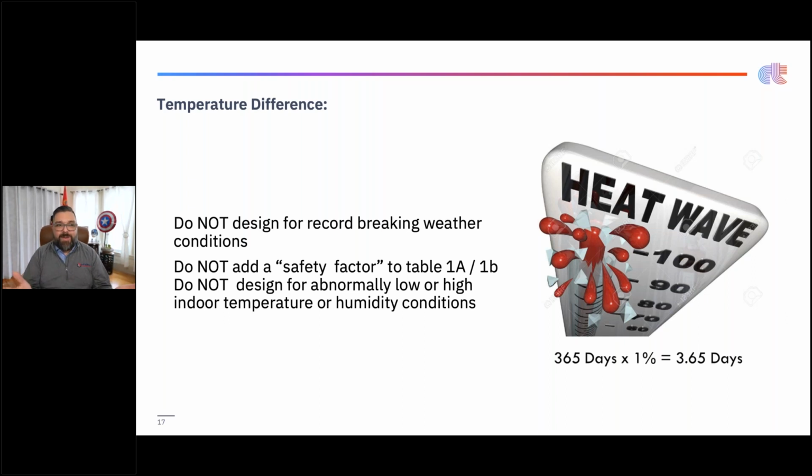All right. It's so simple. You got to use those right temps. And that is one thing that building inspectors do look for. Okay. On the indoor design temps, we actually design around 75 degrees and 50% relative humidity and cooling.